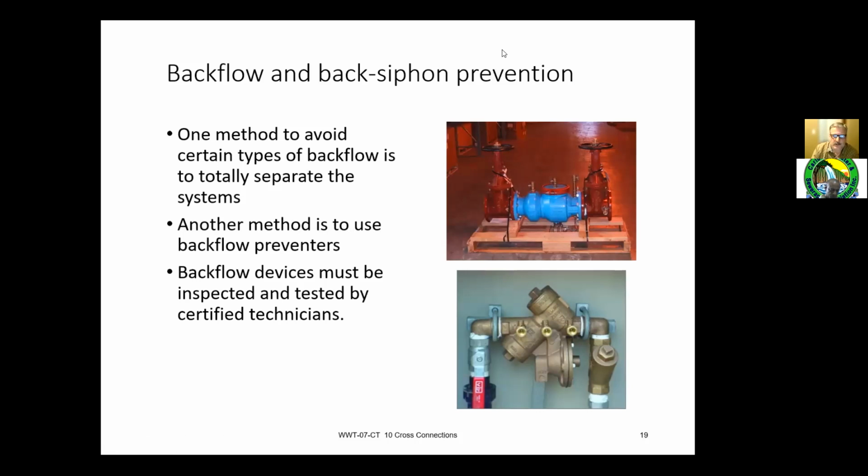Do you deal with any of the backflow equipment or connections on your site? We have a couple of main connections to our main potable water supply from the city. It goes through a double check valve assembly that's checked annually, and I've had some of the operations staff and mechanical staff certified so they can test these. They have to be tested annually to ensure they are functioning as they're supposed to.